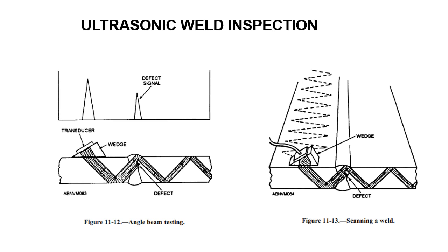If there's no flaws in the weld, you're not going to see anything. But this is why you need a really skilled operator. The number of hours required to become a good ultrasound technician is a lot larger than to become a visual weld inspector or use mag particle or dye penetrant. It's because there's a lot of interpretation involved in, did I just see a back reflection or did I really see a flaw? But this is the general idea behind weld inspection with ultrasonic.